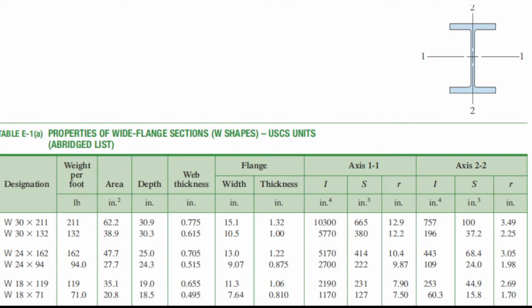As you can recall from last week, we have the curve. The Euler load with respect to the ideal column. And the Euler load is the maximum. That is equal to pi squared EI over L squared.